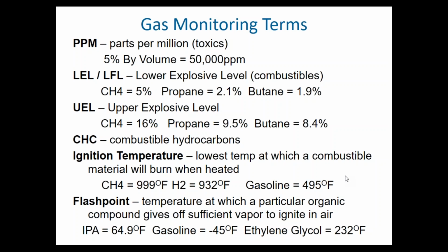One of the reasons why you should be fluent in this is because depending on the industry that you're talking to at a particular application, it dictates whether or not they're talking in terms of ppm, or percent by volume, or percent LEL for combustibles. LEL, LFL. Typically in the United States, we use lower explosive levels, and this is strictly for combustible gases. LFL, lower flammable limit, is a term that's identical, except that that's more popular in Europe.